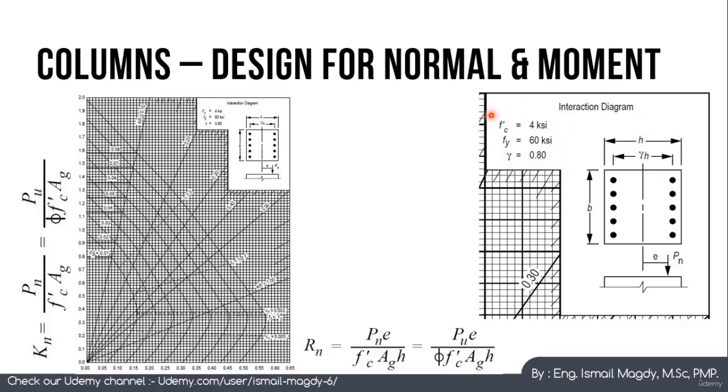This interaction diagram, for example, is for gamma equals 0.8, fy 60 ksi, and f'c 4 ksi. In order to use this interaction diagram, we need to calculate the horizontal component of this graph and also the vertical component. The horizontal component, or what we call Rn, equals Pn multiplied by e, which is the nominal moment, Pn is the normal force and e is the eccentricity, over f'c multiplied by Ag multiplied by h.